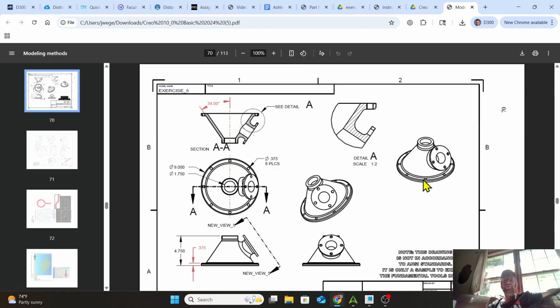We're going to rotate our view so we can see that. So here's the things we've got. We've got this one, that one, that one. We're going to create a sectional view, which again is where we take an object and we slice it down a line that we set, which in this case is going to be essentially a planar section. We cut right down the middle of that thing to create this view up here, which is where we're seeing the result of this cut line on this part. So we're able to see what is represented by hatched lines here, the solid portions of that part.